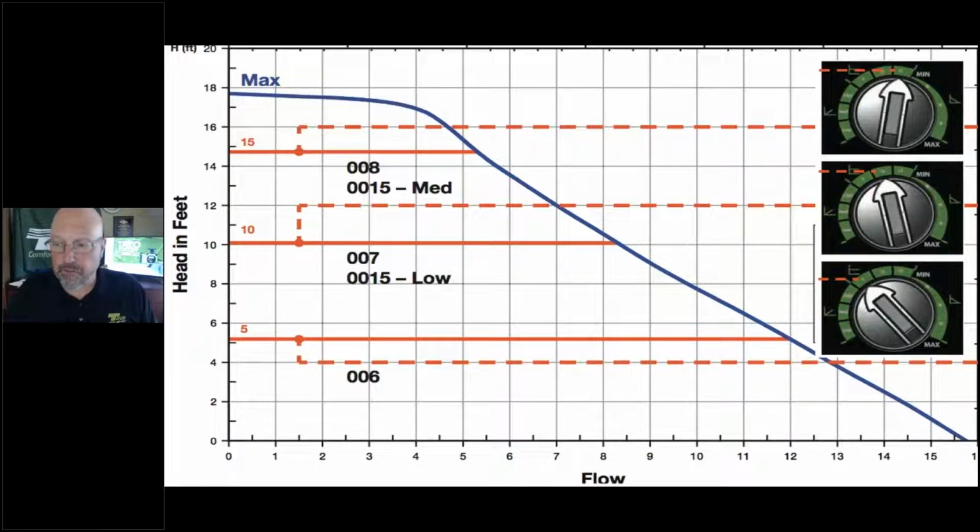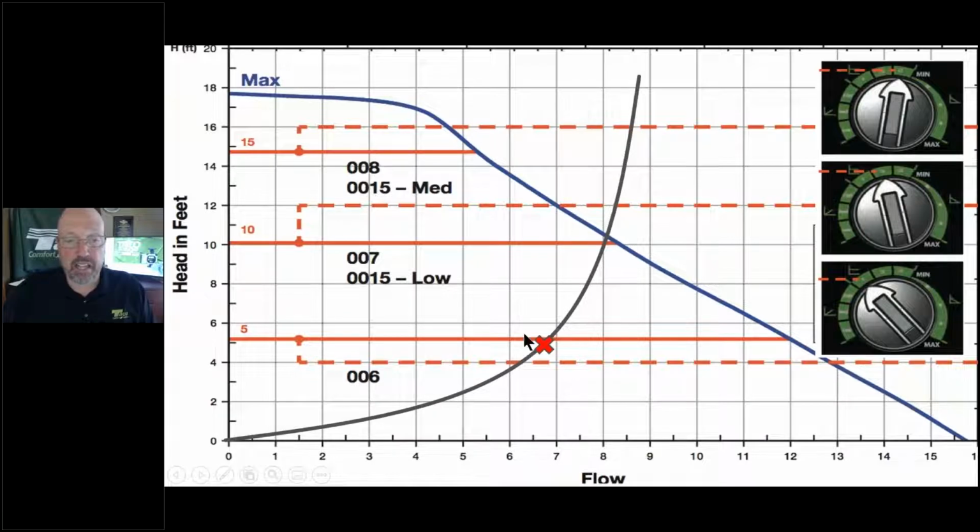So as we follow our application that we were looking at, it's at 7 gallons a minute. If this was a zone valve system, this is my 2 zones running, it'll operate out here. A zone valve closes and it bops back down to here. So this would be our full speed mode of everything that we need. And instead of it running full speed at 44 watts way out here, we're actually really close to our design, and we're running, say, around 30 watts. Zone valve closes, we come all the way down to here.